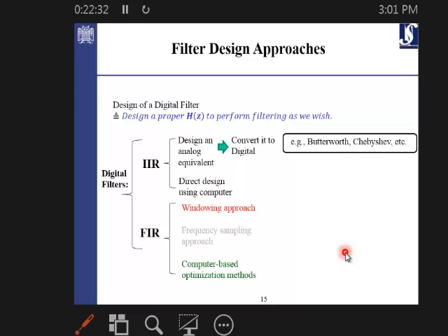So for the IIR case, we always have to study whether the filter is stable or not. Is the degree of the filter, the number of zeros and poles belonging to that filter, such that the filter finally is stable or not? For FIR filters, we know that they are always stable.